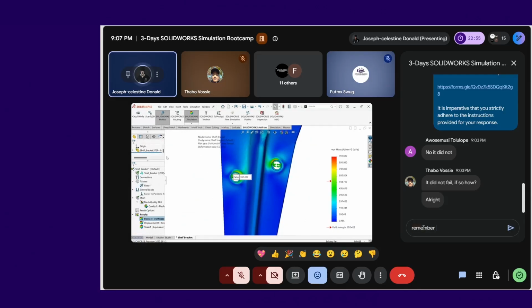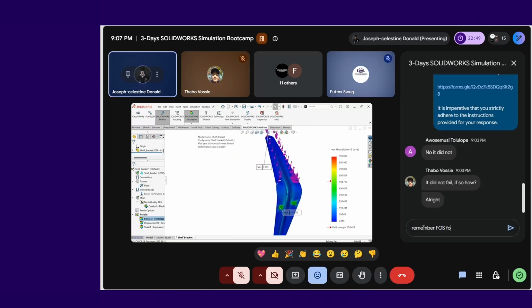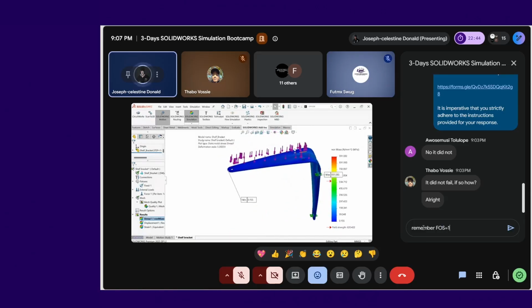Since we don't have time, displacement. Now I can assure you one thing though. To get a different answer or a different value, you can do one of two things. If you refine the meshing for this, you already know it's going to fail. Refining the meshing is just going to show you how the value tilts a little bit, like instead of 91 it will be 93 or 92 or 96, depending on how fine the mesh is.